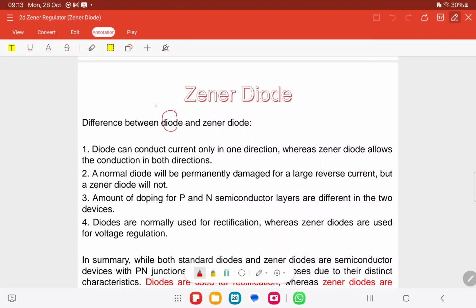For the diode we have forward bias and reverse bias. If forward bias, it is on. Reverse bias, off. On means we have values for ID and VD. If off, there is no value for ID, but VD exists. When on, the diode is a short circuit, so current can pass through. For reverse, it is an open circuit. That is why ID equals 0, because in an open circuit, current cannot pass.